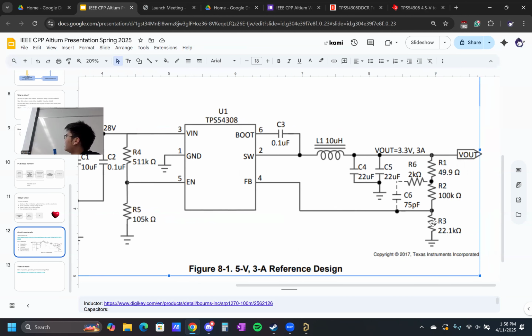Over here on the right, we have another voltage divider circuit. What this does is give the buck converter feedback on what voltage is coming out. If it's outputting too high, then internally in this chip it's going to bring it back down. If it's outputting too low, it's going to bring it back up. The inductor basically turns that switching back and forth, almost a triangular waveform, into a linear waveform for your electronics to use. More capacitors turn that moving waveform into a fixed 5 volt signal. And that boot is there just to boot it.